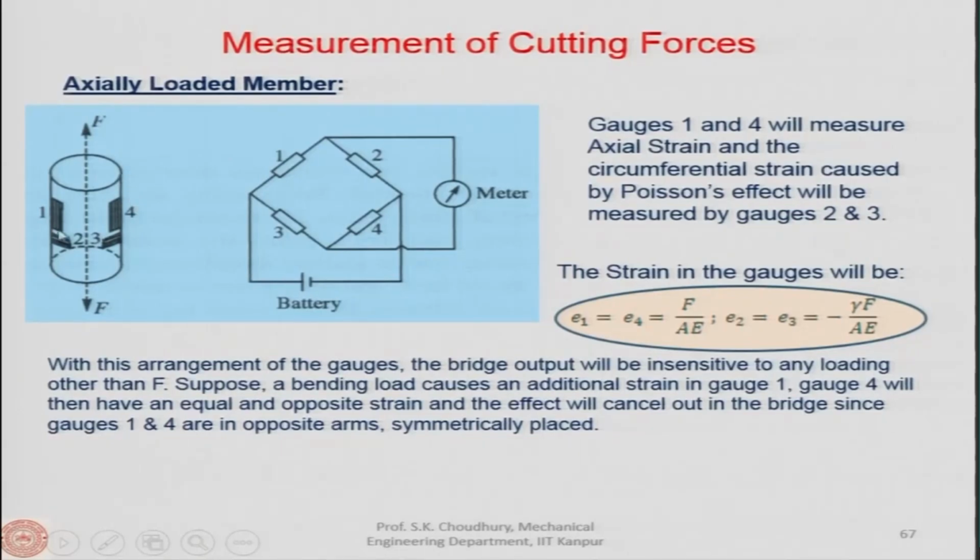Therefore, strain gauges 1 and 4 will exclusively sense the axial force and no other force will be sensed by 1 and 4.